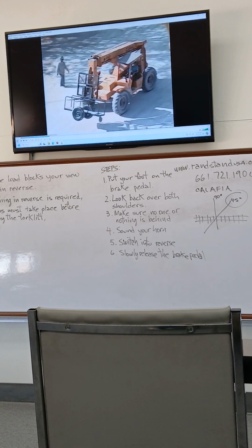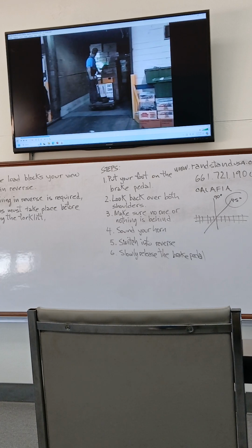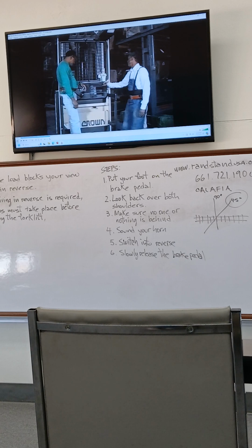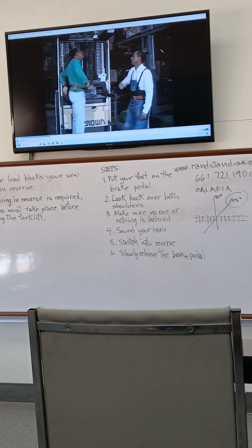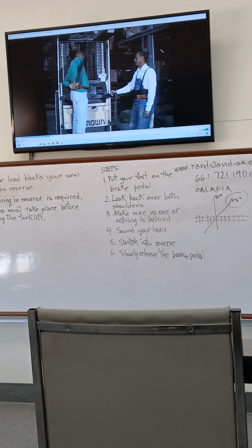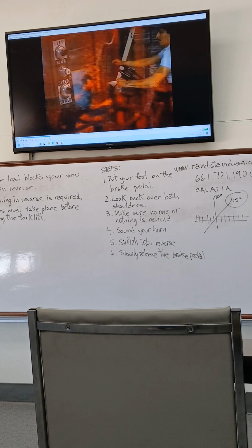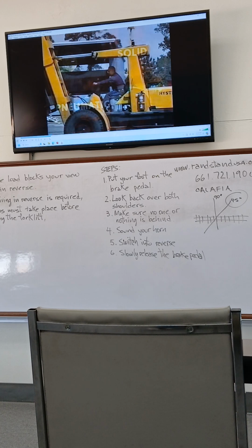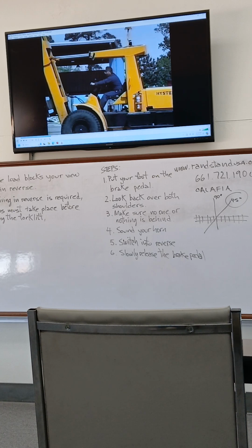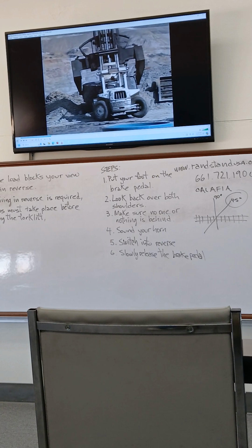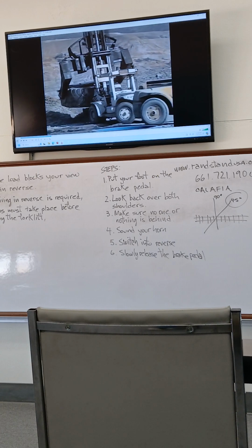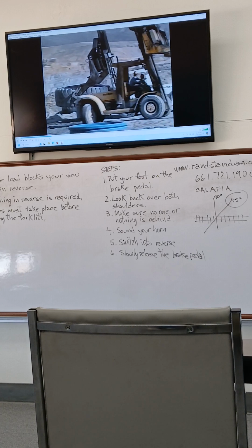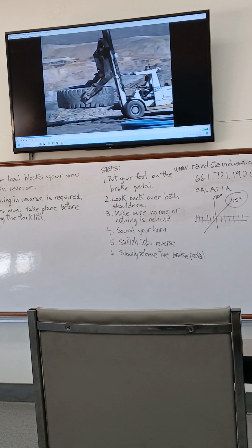Each of the different types of powered industrial trucks has unique characteristics and inherent hazards. To be most effective, training must address the unique characteristics of the type of vehicle operators are being trained to operate. Before we move on, let's take a quick look at solid and pneumatic tires. Pneumatic tires are tires filled with air, just like your automobile tire. They are designed so the forklift can maneuver in uneven, ungraded terrain surfaces. The tires are more flexible and can adjust to the changing surfaces on which they drive.